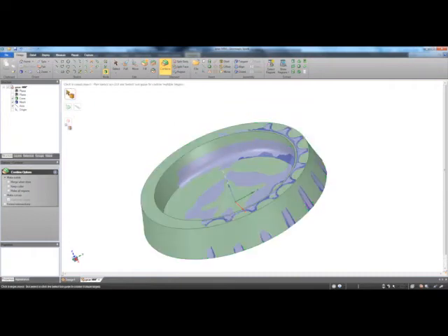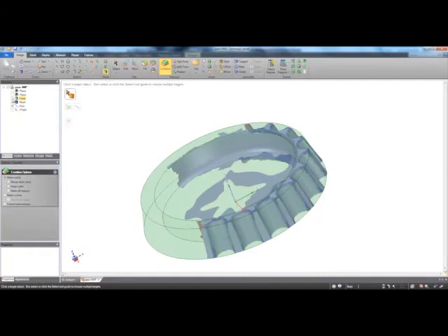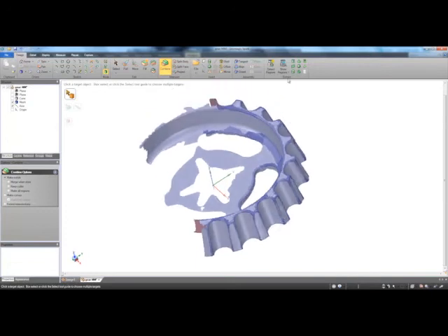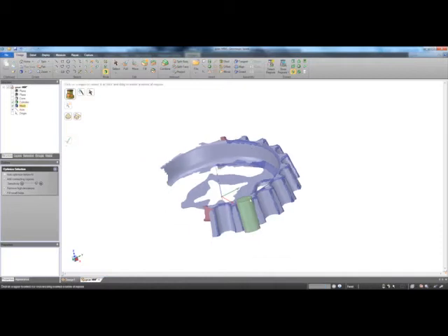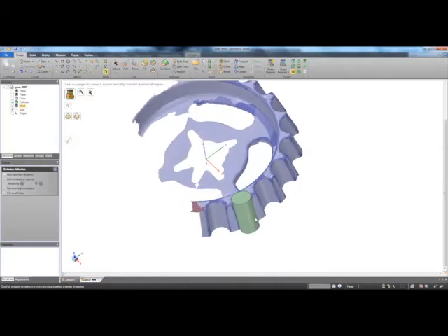And so now I have this main body of the gear that's been created. So let me hide that solid again, and then now we're going to try to fit all the grooves for these teeth. So we'll go to fit cylinder, choose any of these grooves using that select region, and then go ahead and choose optimize and complete, and this will fit a cylinder as expected.